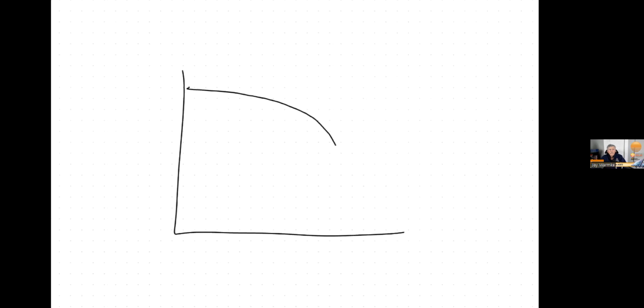All right. So one of the things I said is there's an infinite number of IV curves. So this was the IV curve under standard test conditions. Let's say that a cloud passes over the sun. Amperage is affected by irradiance, and irradiance is how much sunlight is hitting the panel. So if a cloud passes over, maybe my curve changes to look something like that. It affects mostly amps, a little bit of voltage, but mostly amps. Now all of a sudden, it gets even darker. Well, I might have a curve like that.